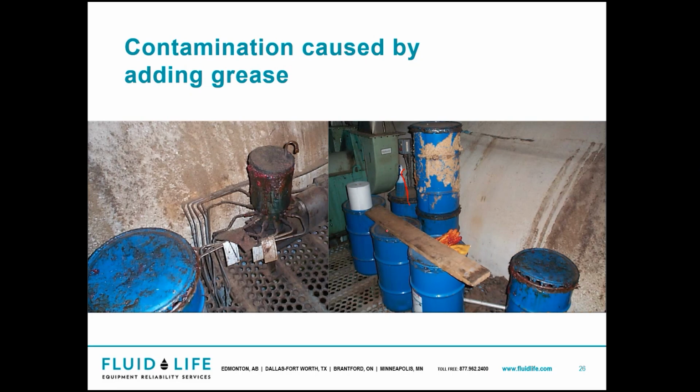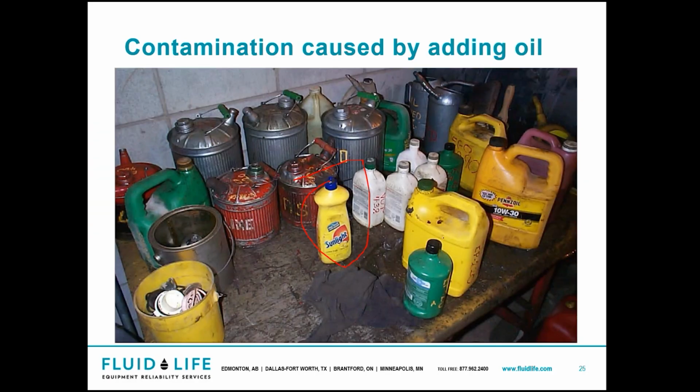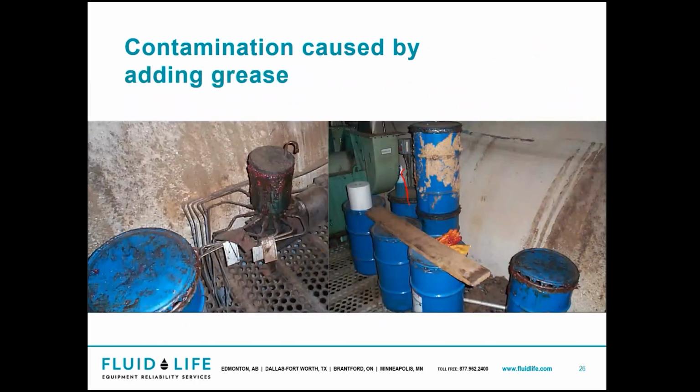And he was hand bombing grease with this glove, which probably came with the Sunlight container here. So I have no problem hand bombing grease. Just use something like disposable nitrile gloves or something. Don't be reusing a glove and leaving it exposed. Grease is especially susceptible to contamination. It's not like oil where you can have dirt drop out of solution, where grease just holds everything there.